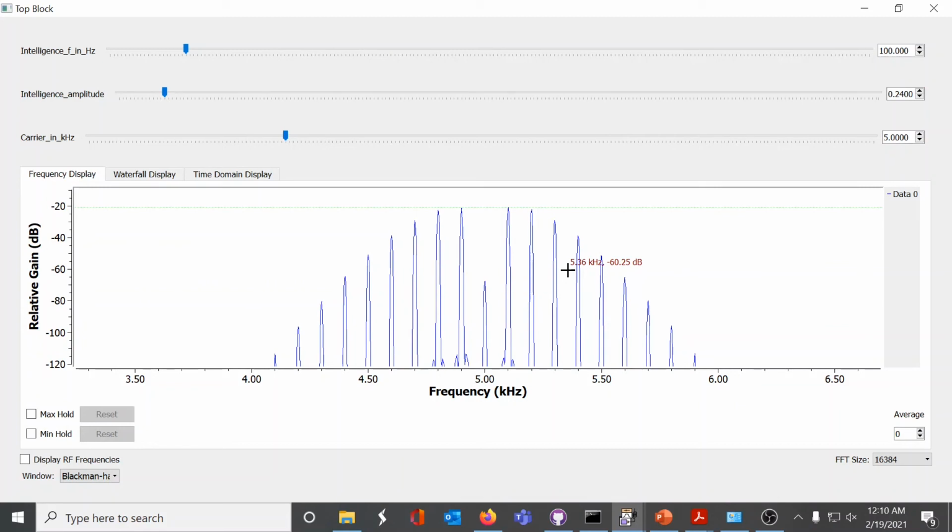Before I forget, go ahead, find your textbook, and turn to the page that describes the Bessel function. Look for the page that has the table of Bessel functions. You'll see that the author has made a determination on what is significant and what is not significant. For example, if the modulation index is set to 2, the author would say that there's a carrier and 1, 2, 3, 4 significant sideband pairs. That doesn't mean that there aren't more sidebands, it just means that they're not significant.